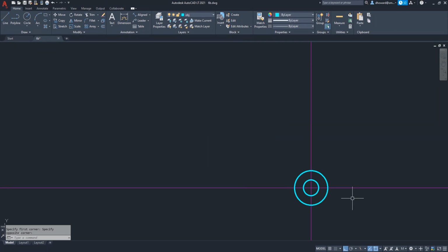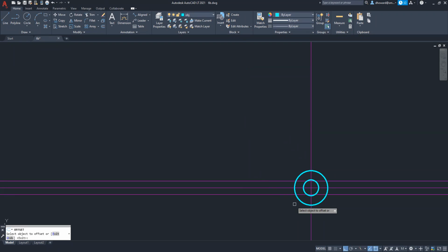We'll start with the lower arm and begin offsetting the arm thickness. So its total thickness is 5/8, so its offset from center is going to be 5/16. And we can do that up and down. There you go. Because we're doing the same thing above, I think it makes sense to do the same thing above.